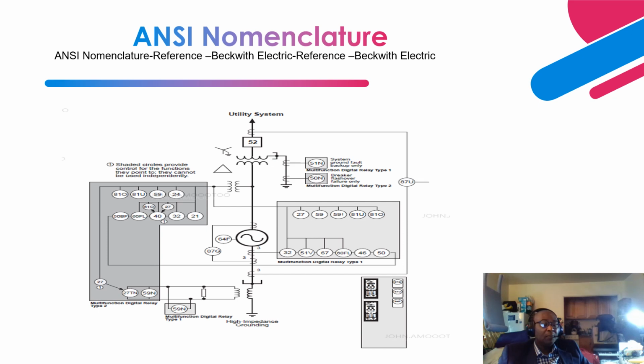24 is volts per hertz, and it measures voltage and divides it by the frequency. Its goal is to prevent overexcitation of the generator and the generator step-up transformer, because overexcitation can cause saturation of the core of the generator and the transformer as well.